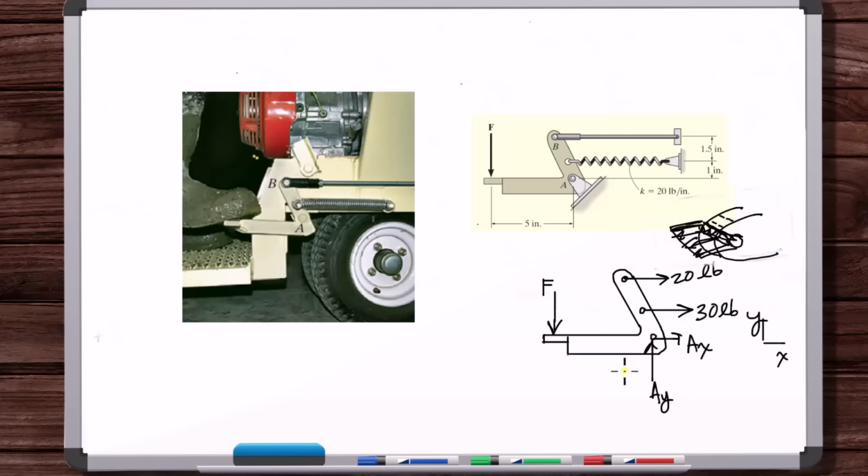Once we find a point of contact and we know there's a force there, we then analyze what kind of motion that force is preventing the body from doing, or causing the body to do. You can think about it that way as well. But with a connection like this, and we'll talk about the difference between a connection, a reaction, and an external force, it's more about what that connection is preventing the body from doing. How is it constraining the body, right? An external force is more about what it is causing the body to do.